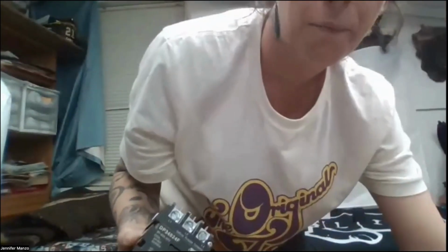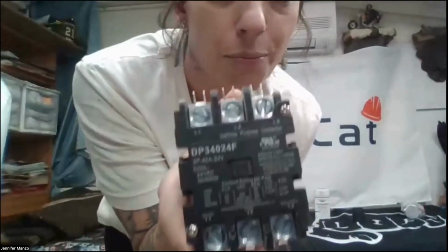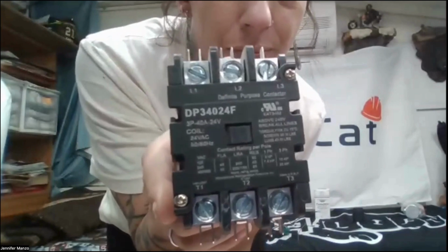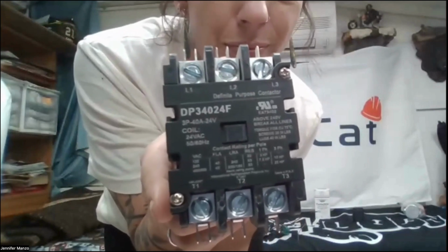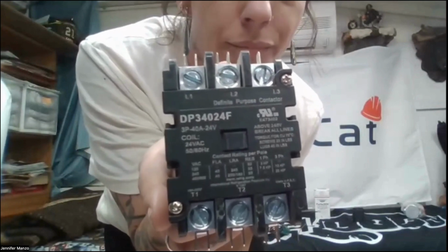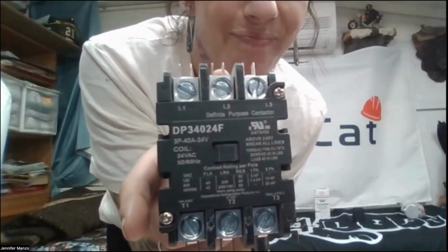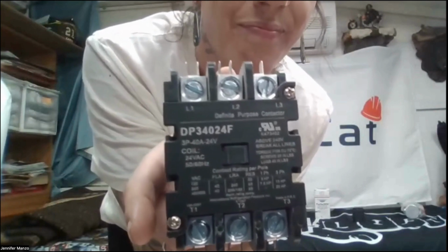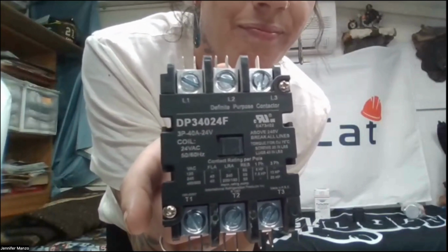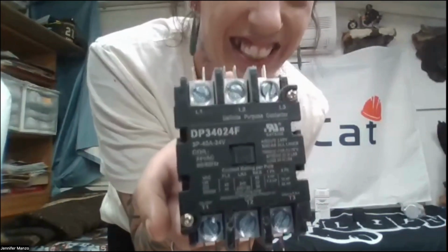I'm a maintenance tech, and a couple times on my stores we're doing RTU units, and when we go to get a replacement contactor, it's the same part number, 3-pole, the whole works. The difference is the cap where you put the wire in is always smaller. So I drill it out. Do you have to do that? That's exactly what I do.